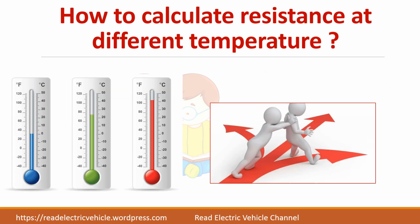So we have already seen that as the temperature changes, the resistance changes. Suppose at 0 degree I know my resistance, but the temperature changes or increases. The motor is running and its temperature increases. Now I cannot go and measure the resistance because the motor is running. Its temperature has increased. So I need some formula to calculate what will be the resistance at different temperatures.